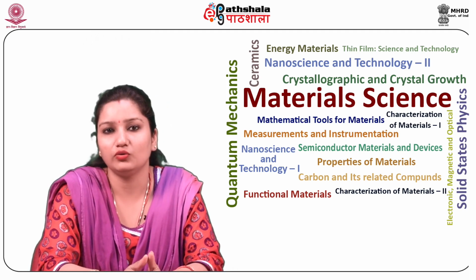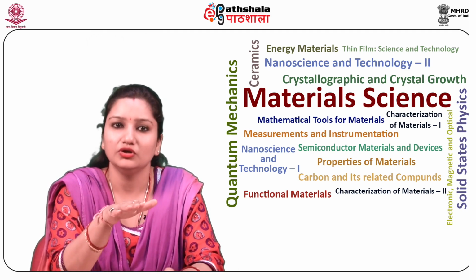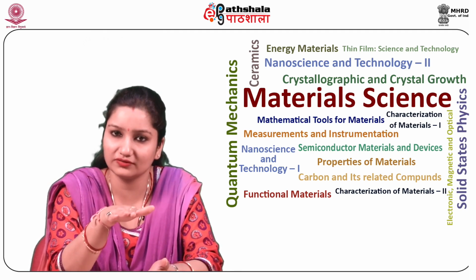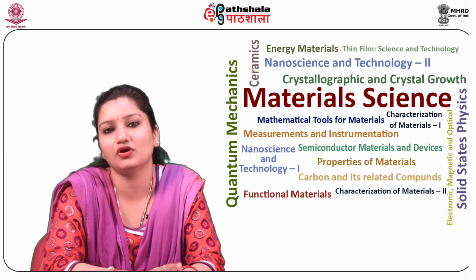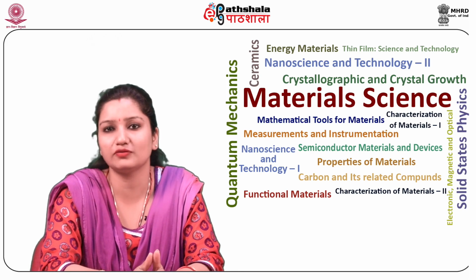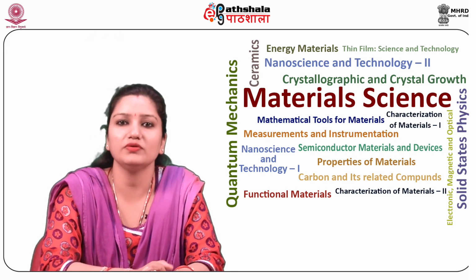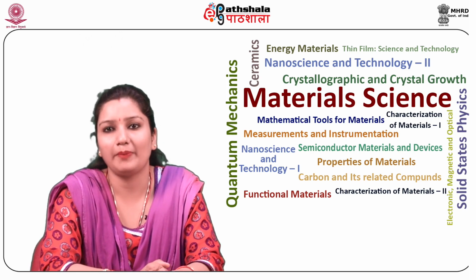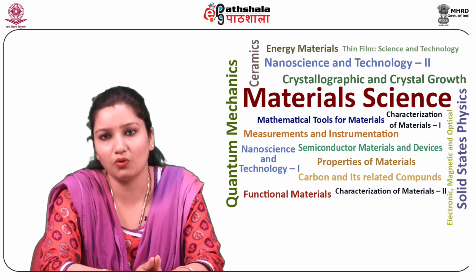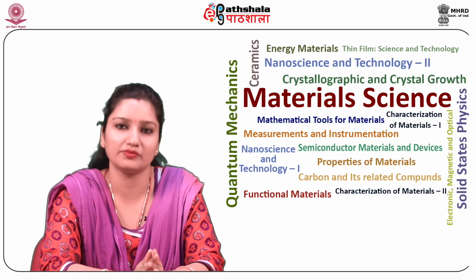Light is used to transfer a geometric pattern from the photomask to a light sensitive chemical called photoresist, or simply resist, on the substrate. In this way, a photoresist pattern is incised on the substrate, which may be useful for incising a pattern of any desired material like aluminium, gold, copper, platinum, etc. on the desired substrate.